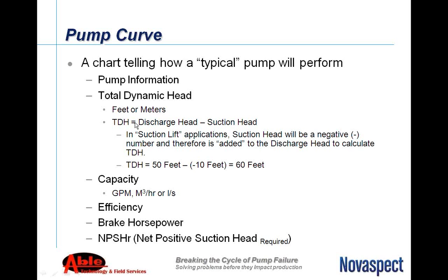Then your total dynamic head, and this little equation here, it's quite simple. I'm going to repeat this at the end of my portion. Your discharge head minus your suction head, or you could go discharge pressure minus your suction pressure and calculate that back into total dynamic head by the same equation.